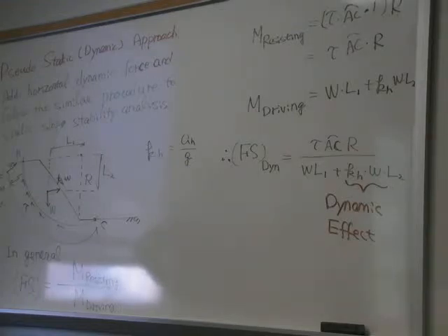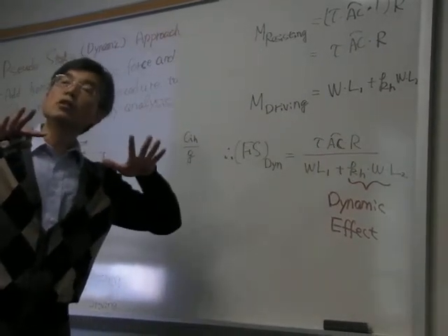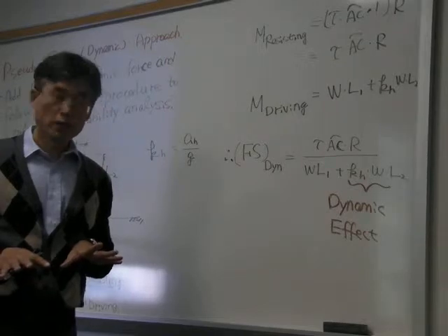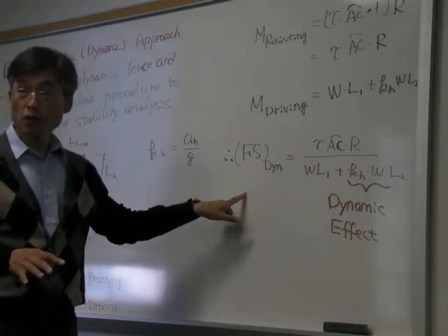That means the slope may be okay during the regular season, but when we have some vibration, then the slope may fail. And many times there is an additional factor for special soils like liquefiable sandy soils. When we have some vibration, our shear strength will become substantially lower. Then this will become even lower, right?